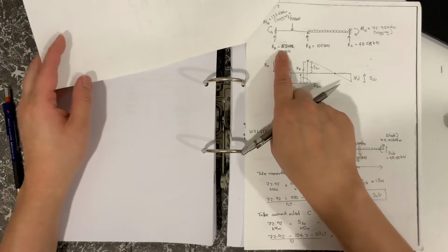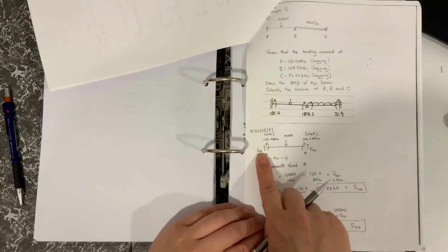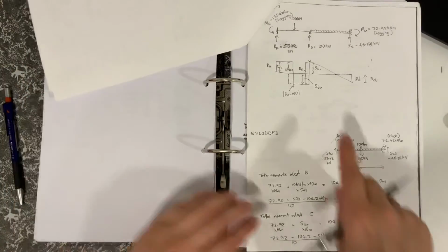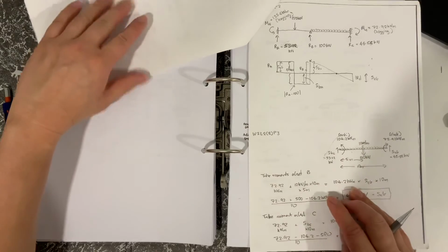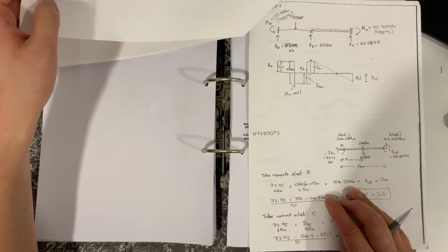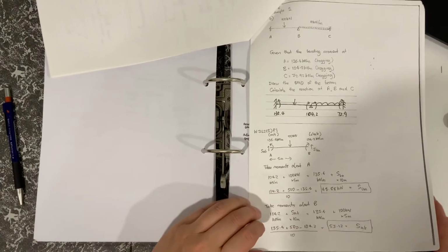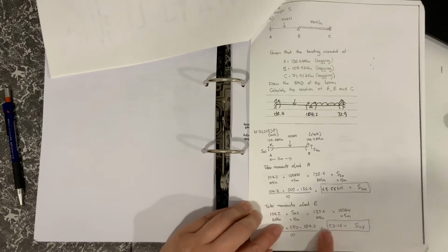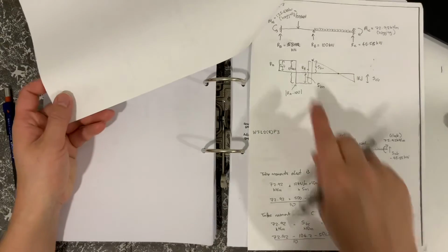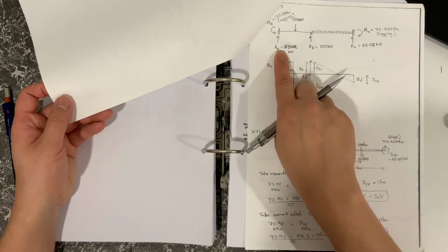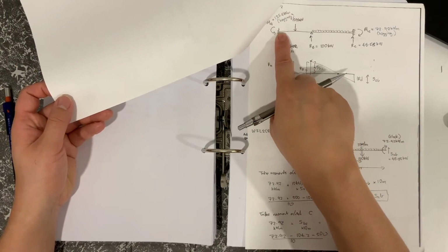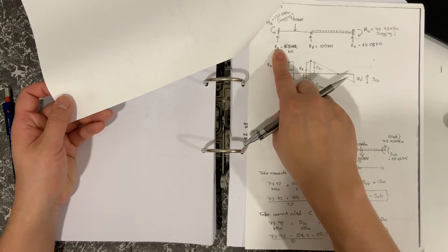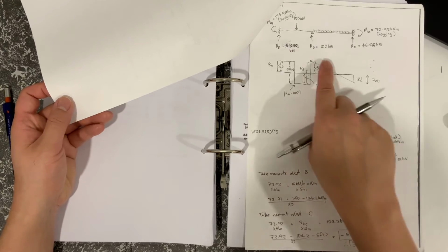So we would work out that SAB, which would be that value there, is 46.88. So SAB, maybe there's a mistake there. Yeah, no, SAB is 53.12. Sorry, I was looking at the wrong one. 53.12, which is either the shear force a hair's breadth away to the right, or it's the reaction. So you can see that written there.